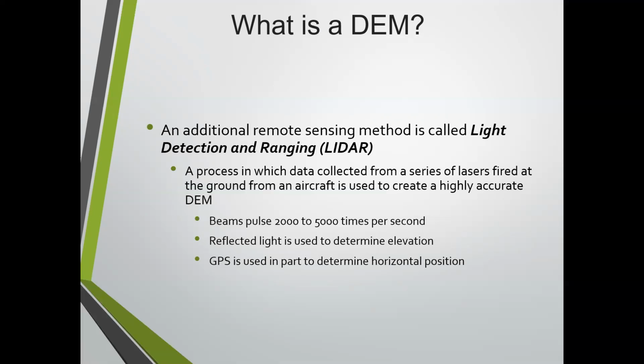So as the pulses are going, you're getting GPS information that's giving you essentially an XY value, and then altimeters, and then you also have the measurements of the IMU information. So it's all really comprehensive, very good data. It's going to provide a really highly accurate data set, XYZ coordinates.